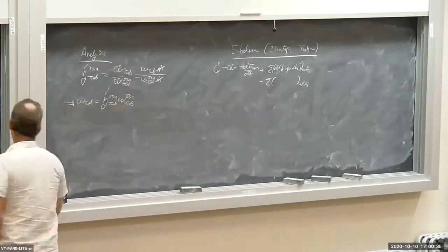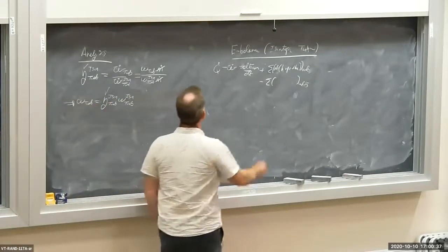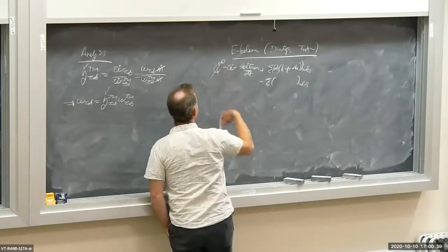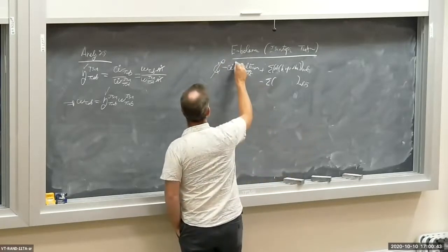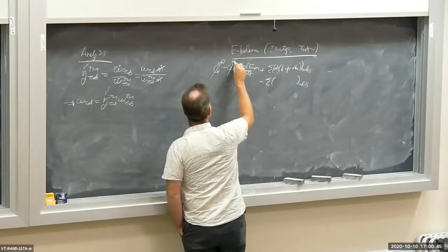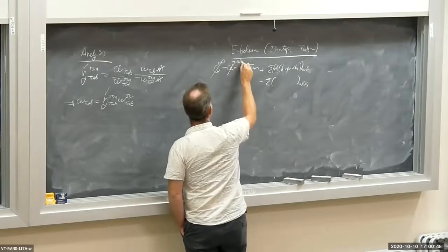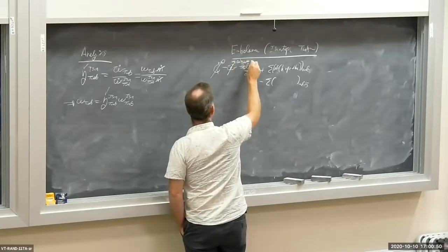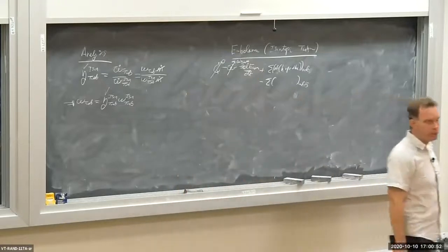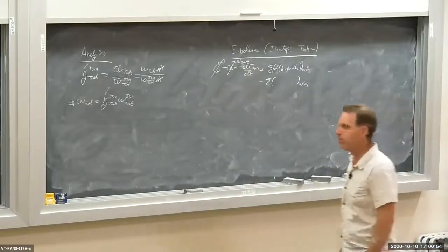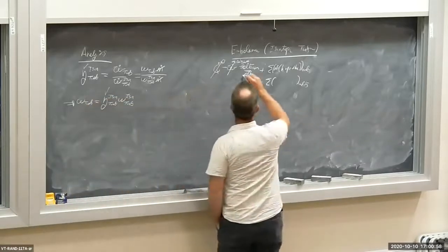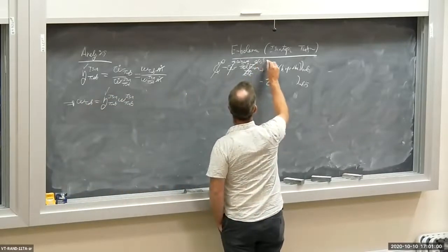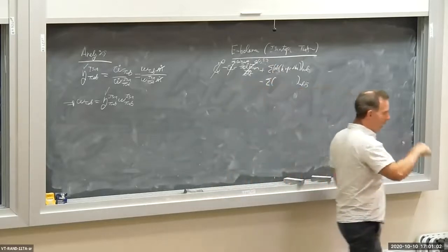Now this is an adiabatic turbine, so this is 0. There's only one form of work, and that's turbine work, or shaft work if you call it that. So this is W dot shaft. It's producing shaft work. That's what the turbine's doing. It's got a propeller in there. No change in energy within the turbine. It's steady state.